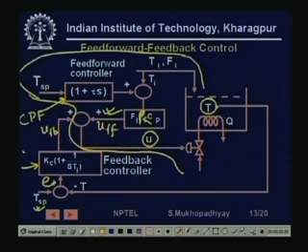If it is a little less, then some control error will now build. That control error will be sensed by the feedback part and that will provide additional input. So if due to modeling error the input falls short, or becomes larger than required, then the corresponding compensating correction will be given by the feedback input and the overall input will be just the right one.